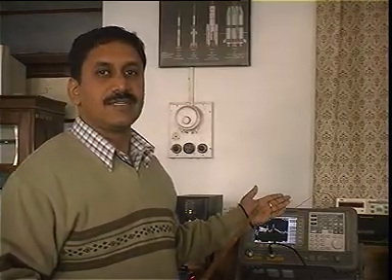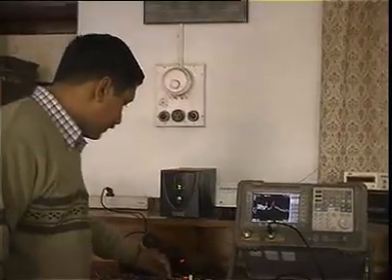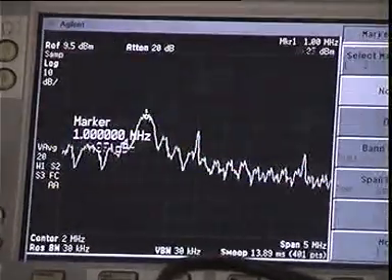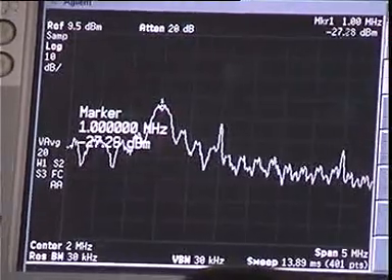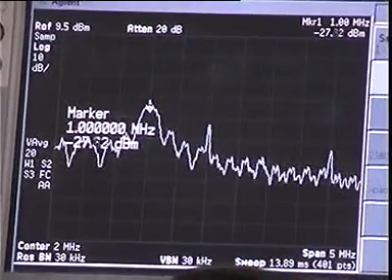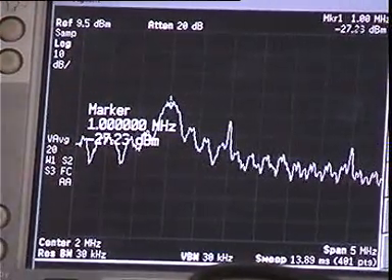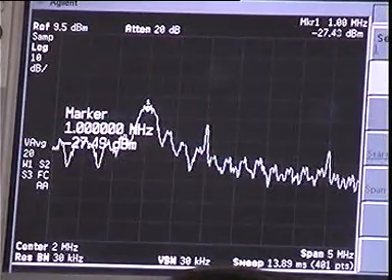I'll only see a sinc square spectrum centered around 1 megahertz. Let us verify that. Right? That's a sinc square spectrum located at 1 megahertz. Okay, so the phase information is lost. I'm only having the magnitude information. I'm using a carrier of 1 megahertz frequency, and therefore this spectrum is located around 1 megahertz. So this is the way we will analyze the digital signals, the time domain representation and the corresponding spectral representation.